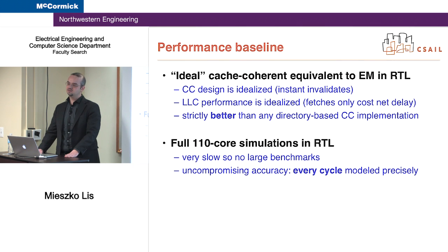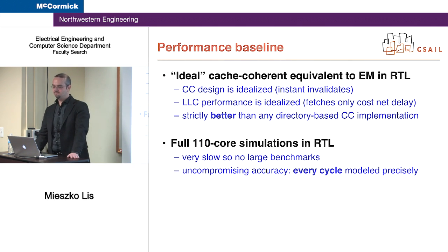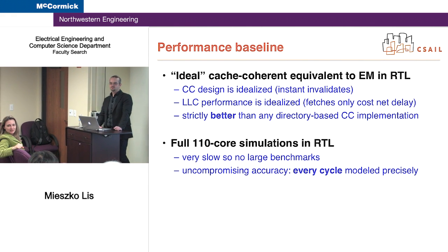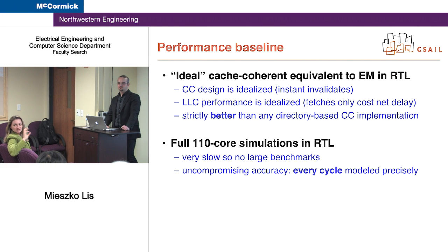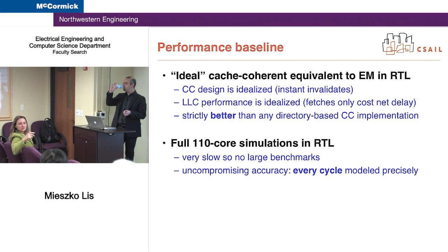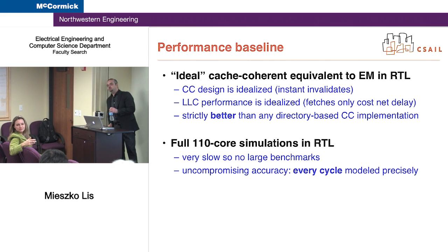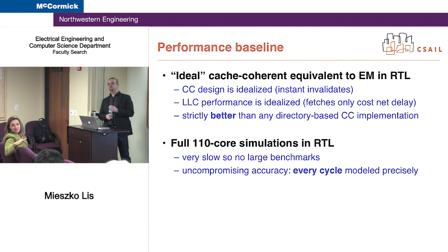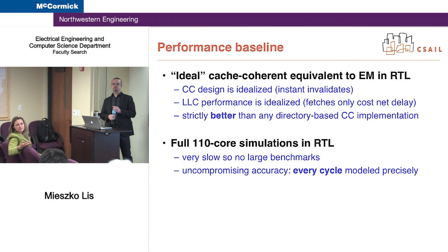Right? So yes. If I may just comment on it. Sometimes, even if you had zero time to bring data to a certain spot, you just don't want to do things all the way in the same location of the chip for various other reasons, to distribute power density. Yeah, you could cook it, for example. To distribute heat evenly. So even for those reasons, you may still want to do thread migration at various times. So even if your data communication was no problem whatsoever, you had that technology, I think you would still want to do thread migration for other reasons.